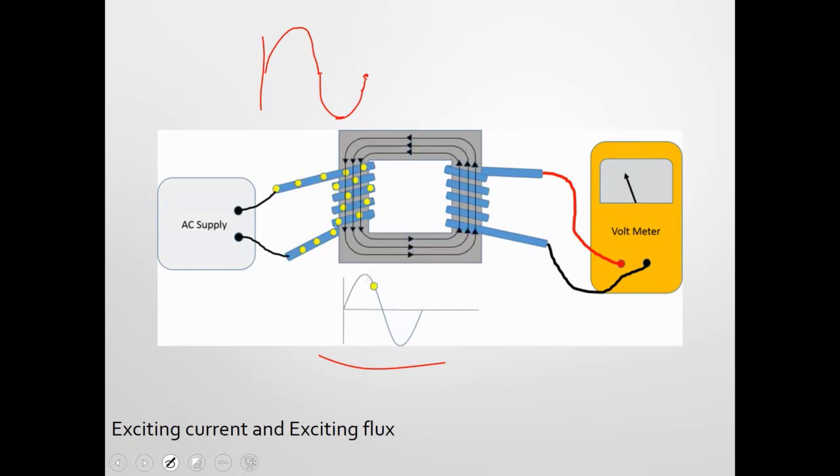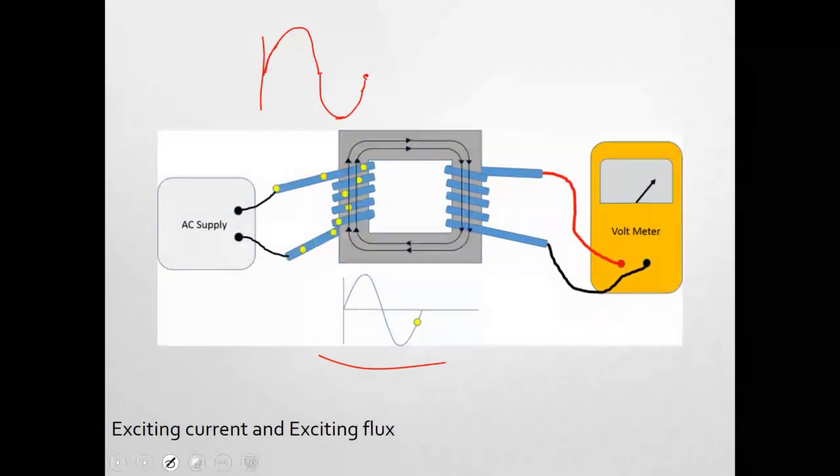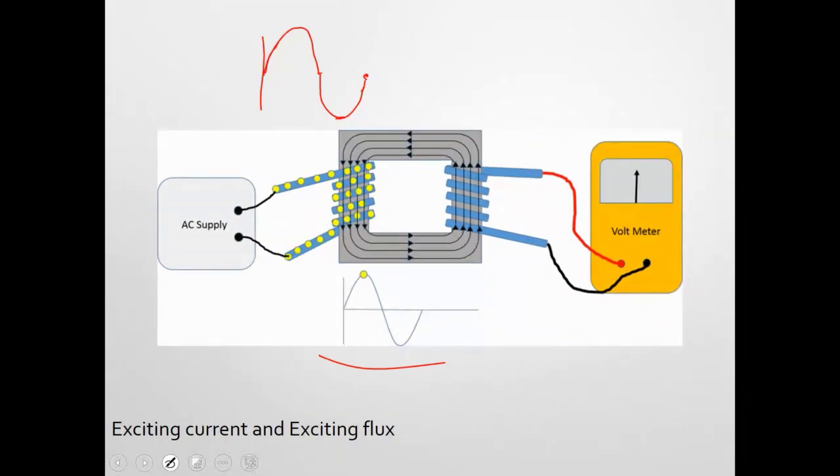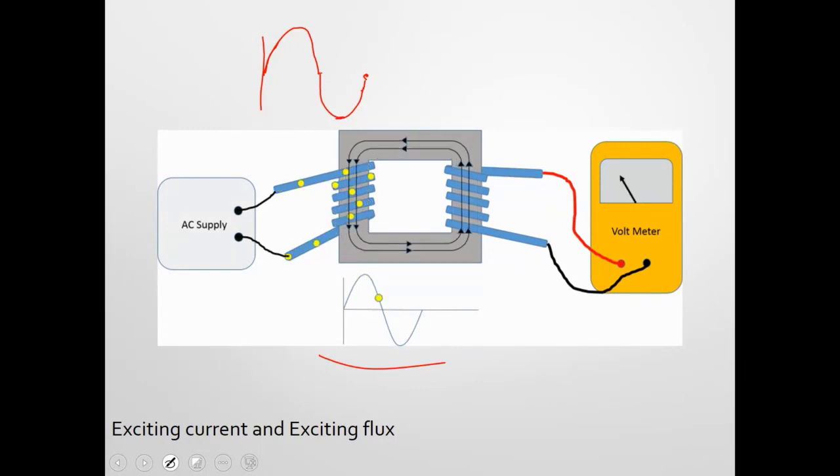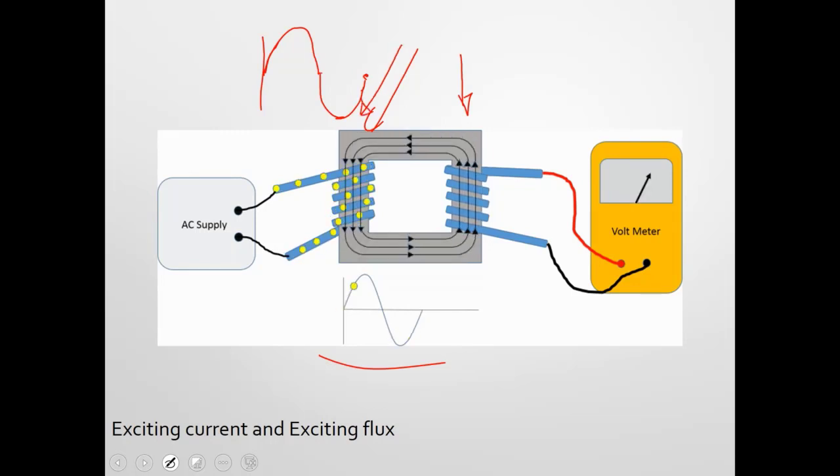As current flows through this circuit, it increases in intensity, and with that increase in intensity, the magnetic field gets stronger and expands. That expanding magnetic field cuts across itself right here, as well as cutting across the secondary. When it cuts across the primary winding, it creates that counter EMF. When it cuts across the secondary, it induces the secondary voltage.